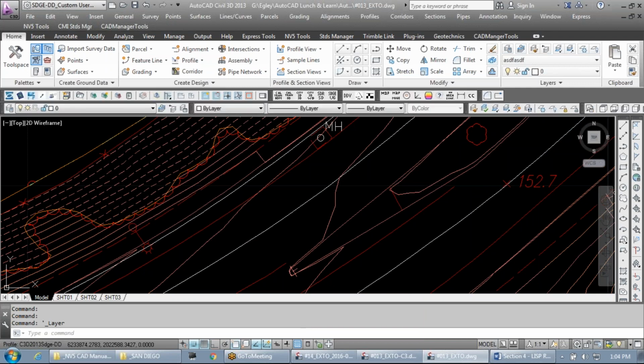So if you undo, it'll erase the layer state that you made? Yeah, of course. Just like any undo. So would you advise saving after you make a layer state? You wouldn't have to. I just hit undo a bunch of times. One of the issues with that CC command is sometimes you have to regen between the commands updating. It's kind of like line types and points. Sometimes after you make changes to your point groups or the styles, you have to regen before they take effect. I hit undo one extra time, so it wiped out my layer state.